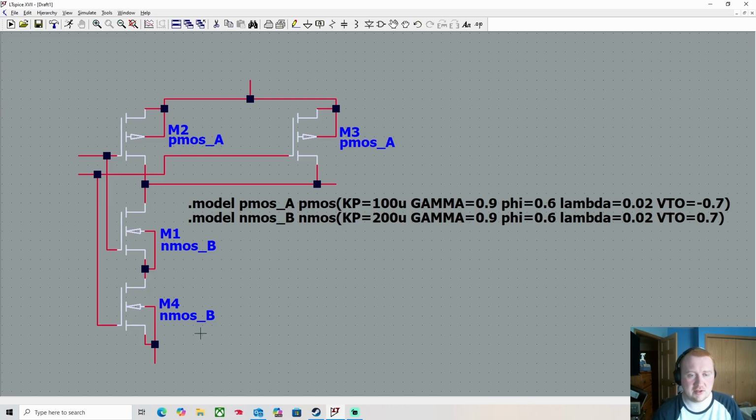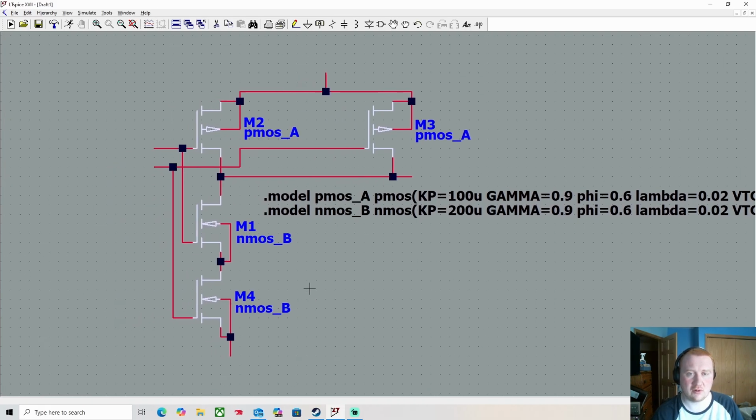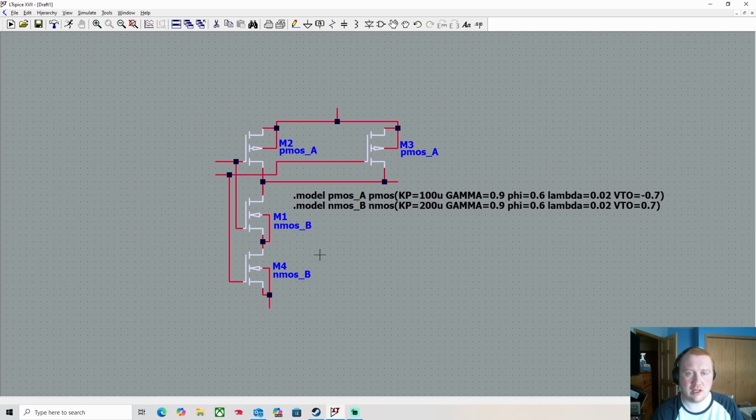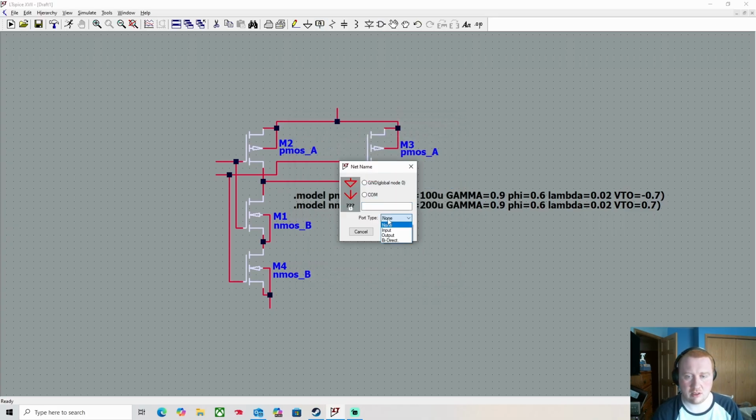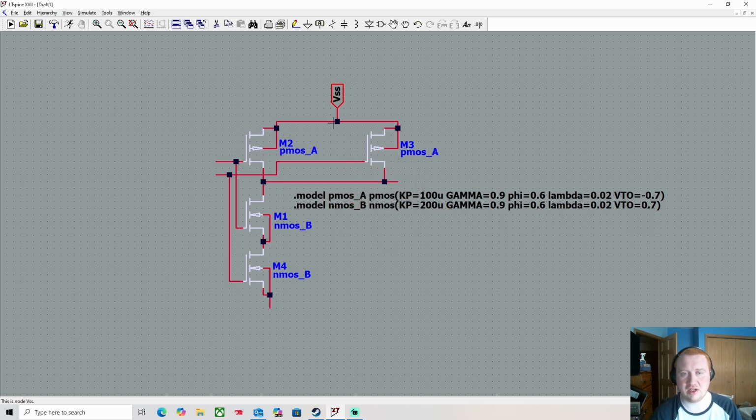So anyway, now that we have this kind of setup, we can add inputs and outputs and voltage sources. Clearly logic gates need some kind of power, so we need positive power and negative power, and usually this ends up being ground. So the best way that I like to set it up is, oops, not that one. Might as well call voltage an input. It's not technically one, but I'm going to call voltage input VSS. That's very common on electronic data sheets.